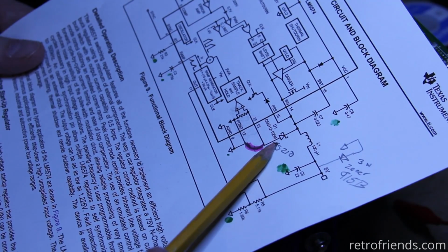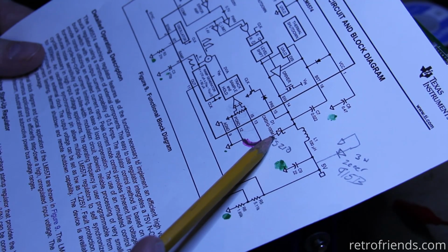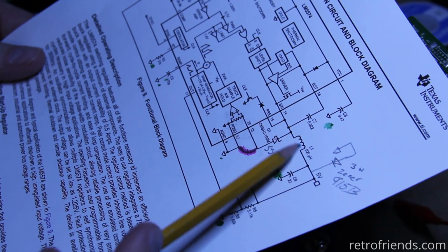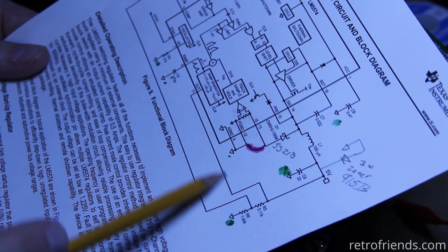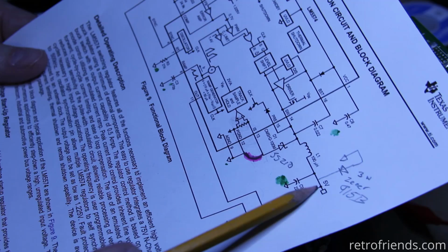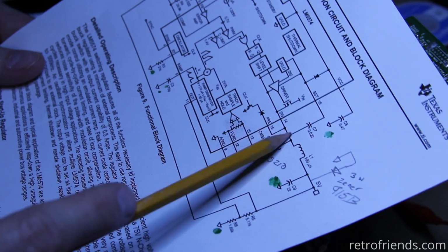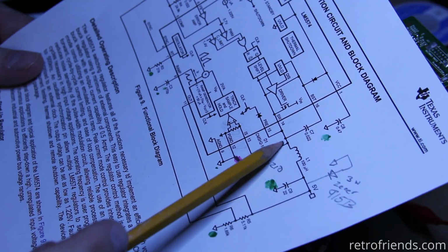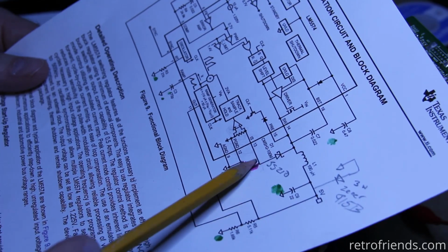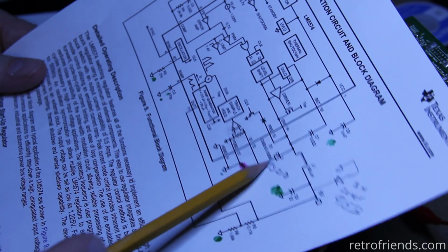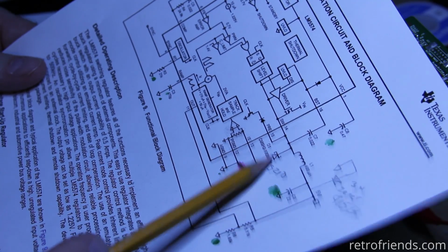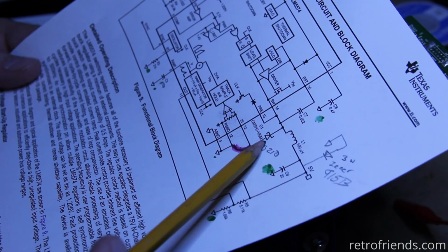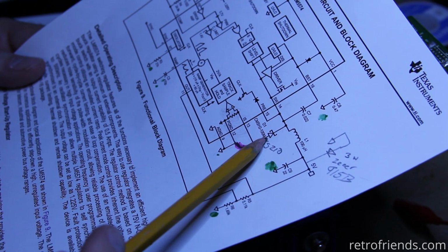I began looking at this diode because this diode was just on the other side of this inductor from the 5-volt output. The 5-volt output actually comes this way. And then I guess it's fed back in with this inductor into the chip for 5 volts to provide all this stuff, whatever it is. And then there's a diode that separates it, and of course one side of the diode is connected to ground, this way. And I actually found that this diode, it's a Schottky diode, was actually open.